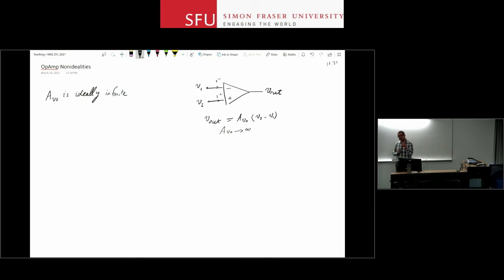The op-amps that you use in integrated circuits are usually made of maybe in some cases only 3 transistors, but maybe 5 or 10 transistors. And because they are so simple, they will have limited gain. So usually a gain of 1,000 is quite a lot. Maybe a gain of 100 or a few hundred is more common. Nonetheless, even with a discrete op-amp, you have a limited gain.